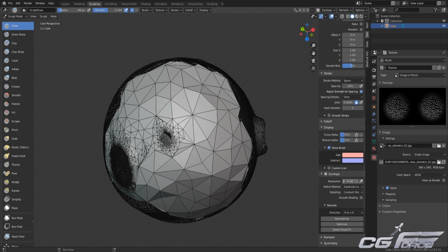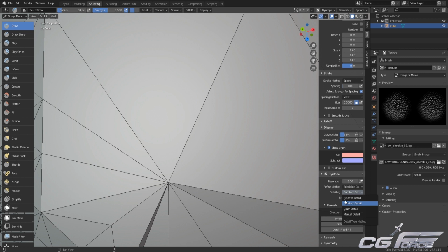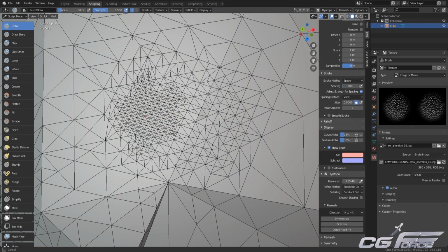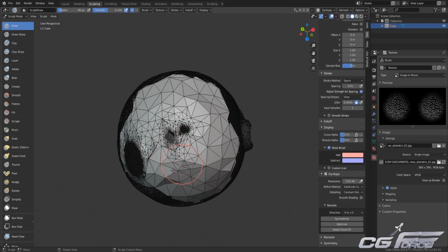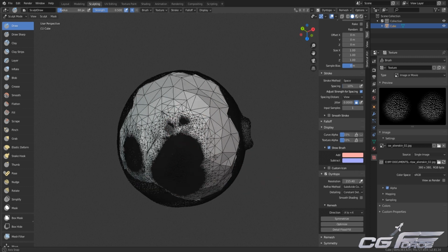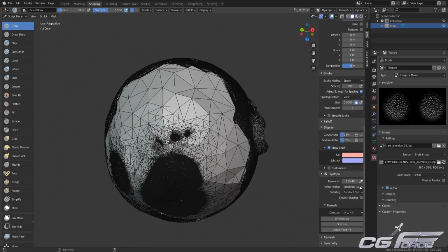which is actually going to help you add only that specific resolution, and it does not depend on the distance from which you are using your brush. By the way, when you're going to use constant detailing, the resolution style of this constant is completely opposite to the relative. I mean, you're going to add more resolution when you crank up the resolution like that. And now you can add more resolution to your 3D model. See? And if I go back, you can see it is still adding that same resolution, 250 resolution on your 3D model. It doesn't depend on the distance at which you've been working.